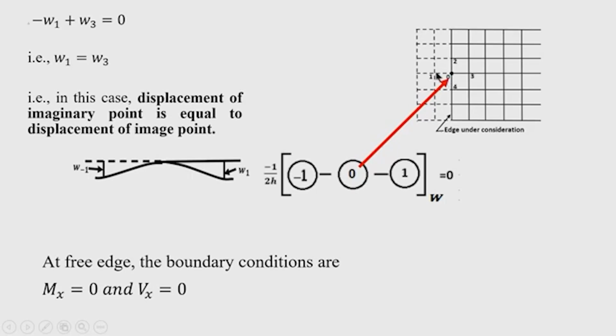0 is the node where we want to apply the boundary conditions. So, for the fixed edge, that is the slope, this first derivative stencil is put here at 0, and then we get 2 points. This point is on the node on the boundary, so automatically it vanishes, because the deflection at the boundary is 0, but this node is outside the boundary and with coefficient minus 1.